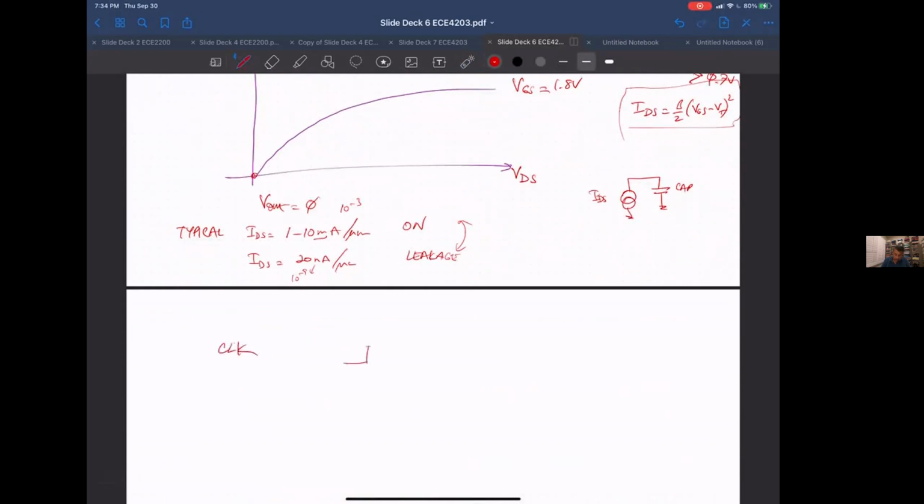The clock is basically transitioning like this. Any other thing, let's say we had data, is only going to typically transition at the rising edge of the clock because you have flip-flops, etc. So the fastest data is going to have fewer transitions than the clock.